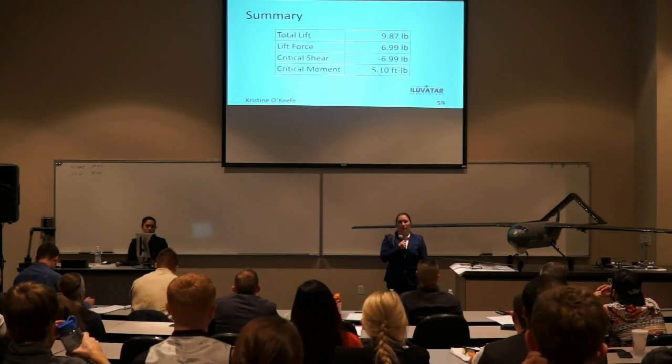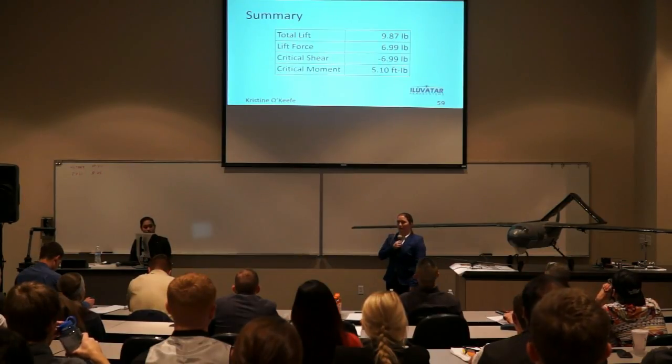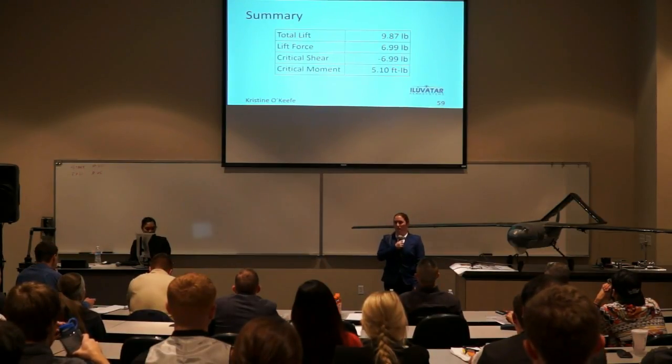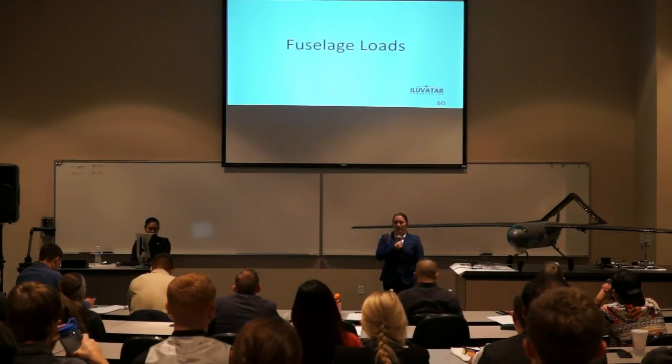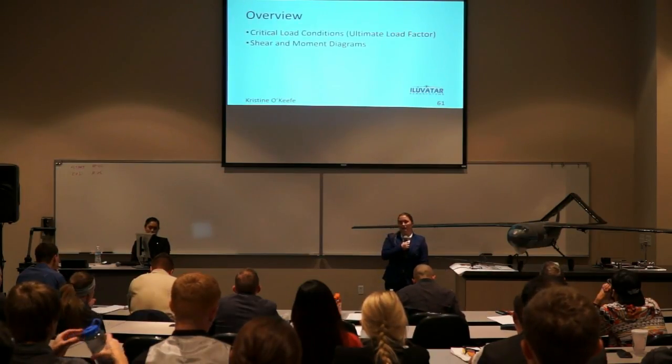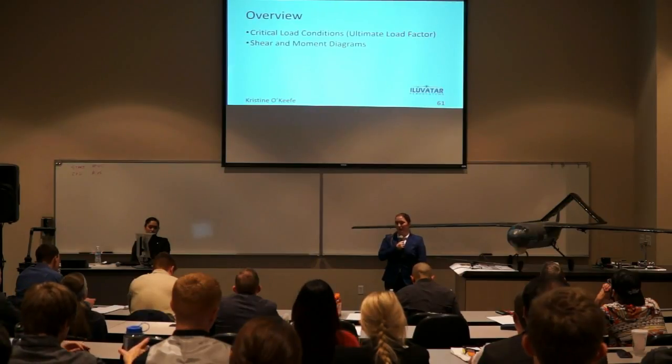So here's the summary of all the loading that will be acting on the empennage and will be used with Josh Parr's empennage sizing section later on. Then we can move on to the fuselage loading. This is based off the critical load condition and the shear moment diagrams.